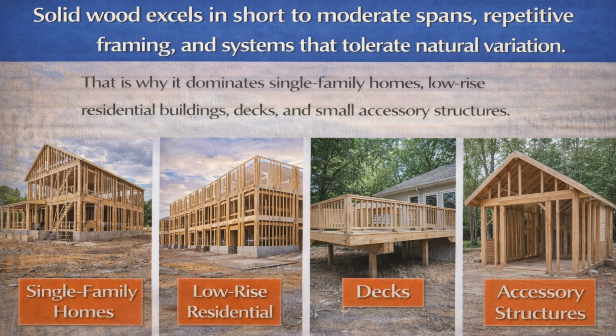Professionals never choose materials in isolation. Every project eventually asks the same question: is solid wood the right material here, or is this the point where another system performs better? Solid wood excels in short to moderate spans, repetitive framing, and systems that tolerate natural variation. That is why it dominates single-family homes, low-rise residential buildings, decks, and small accessory structures.